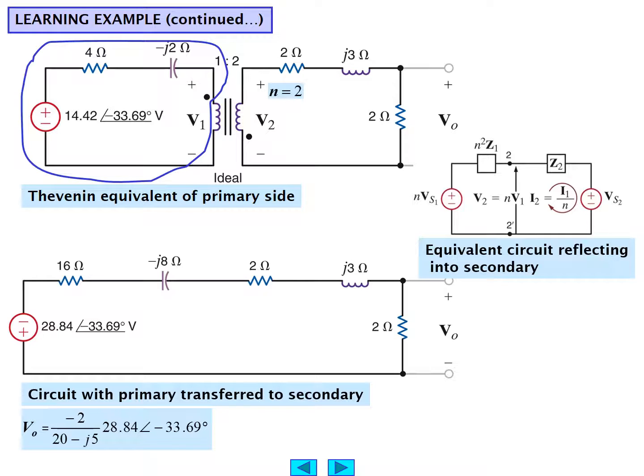It should be noted that the voltage source has changed sign. In other words, the positive sign of the voltage source in the primary is now on the bottom, used to be on the top, and that's because of the dot notation on the ideal transformer. If the dot notation were on the same sides, it would not have changed sign, but in this case it does, and that's how it picked up a reversal, if you will. So therefore V0 now has a negative sign in it as a result. Doing the calculation in complex algebra, we can produce a result for V0 by manipulation correctly, hopefully.